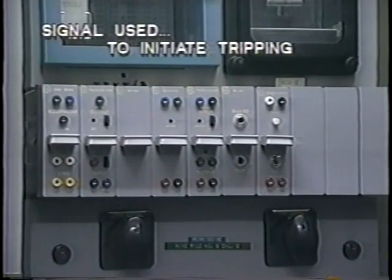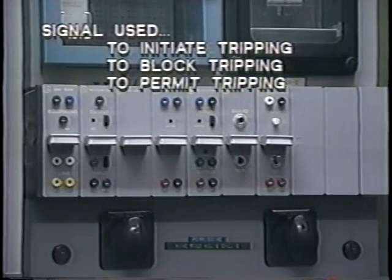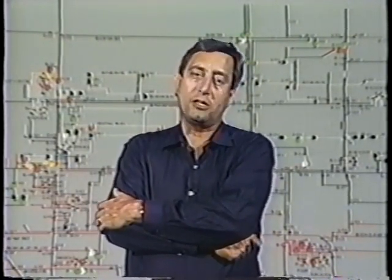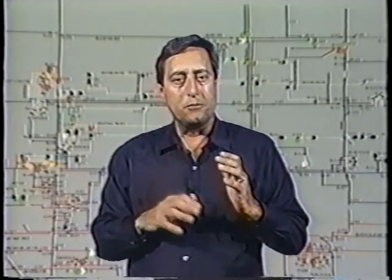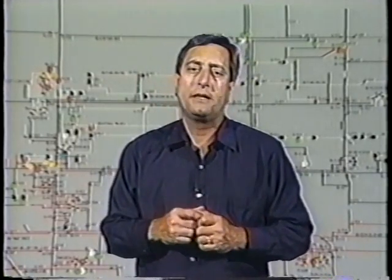To initiate tripping, that is, direct transfer tripping. To block tripping, or to permit tripping. In your workbook, we have included a summary of the various pilot protection schemes in common use and their preferred communication channels. Take time to study and learn this information, and make sure that you study the pilot protection schemes that are used in your own power system. Check out the relay settings and also the logic diagrams with your supervisor. Please switch off the tape now and thoroughly review this material in your workbook.